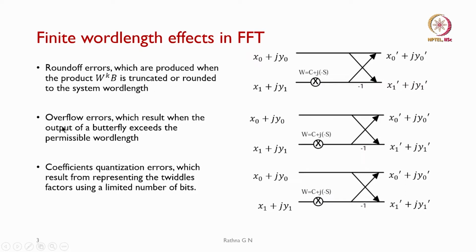The next one is the addition, which is going to cause overflow errors. This results when the output of a butterfly exceeds the permissible word length. As you can see, there is an addition, so when it exceeds the limit, we will have the overflow.